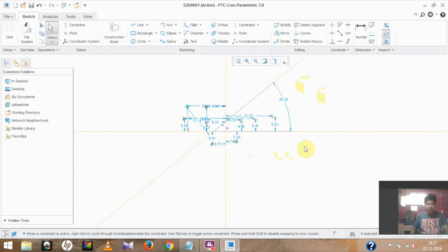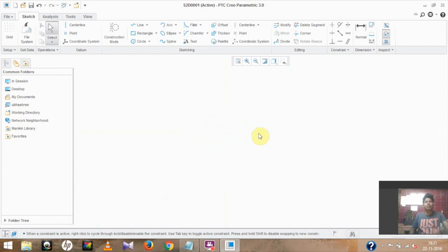So in my next class I will tell you how the dimension is created and how to modify your dimensions. Okay, so no need to worry about this. Click the selection key with your MB1 button, just drag on this area. Now you can see the color is changed. That shows that all the features we drew in the graphics area have been selected. And just press the delete button and you can see all the points are deleted.